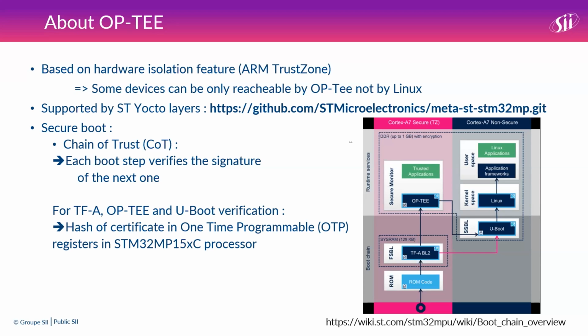I see a question from Mark, a question about TPM. Okay, maybe just Mark's was before, on the M4. Okay, he answered. Yeah, you could do some prints also. On the M4, in fact, with the device tree, you could set up which peripherals remain to each. You could have peripherals especially for secure worlds or for OP-TEE, peripherals for Linux, and you could also reserve some peripherals for the M4. You could specify a debug port for the M4, the same way you could have a debug port for the console shell for Linux. So you could debug that way. But there are also JTAG and a lot of other stuff.